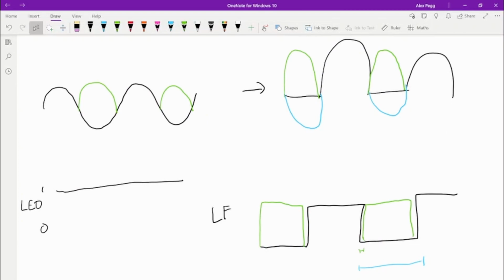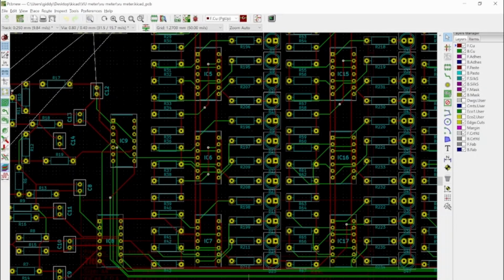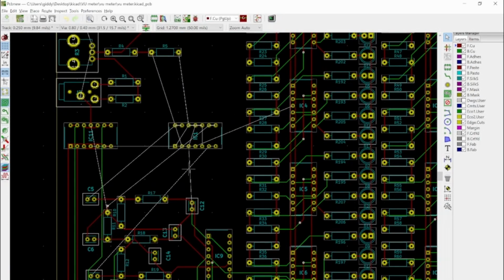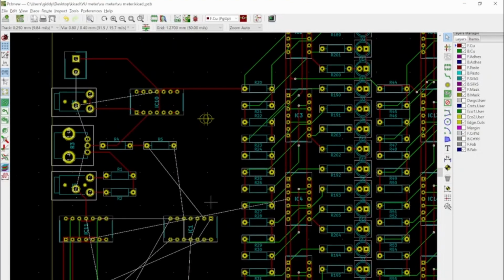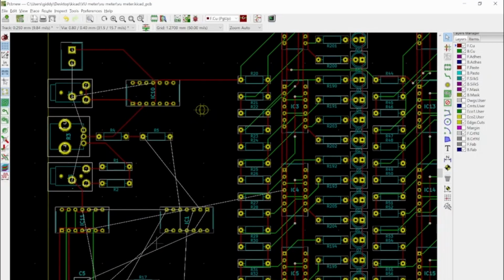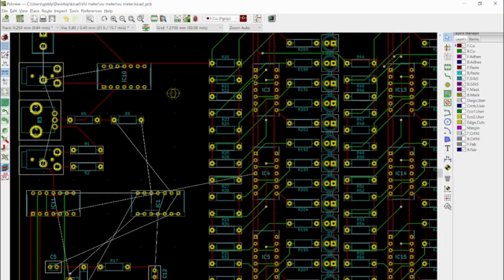The other final improvement that I'd like to make from making this board is this PCB. So ignore that one of the chips is missing, but this was my first design. When I first designed it, this chip here was upside down, so the pin 1 was up at the top, but I'd put all the other ones with pin 1 in the bottom left corner. So when I soldered this one on, it was upside down and backwards, so it got hot, overheated, burnt itself all up, and then shorted between power and ground, which was not good. So that's that.